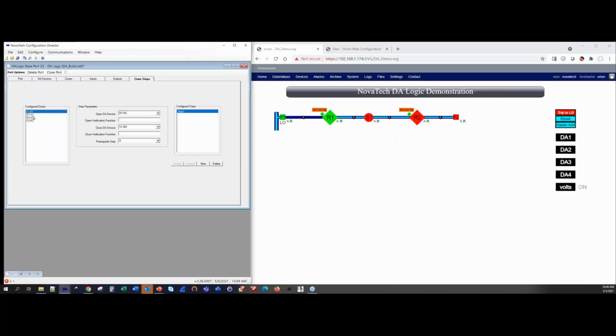Okay? For feeder R2 or zone 2, if there was a fault here, protection would open recloser R1. Switch 1 is already open. We're not going to bridge anything, so there are no steps associated with R1 to S1.